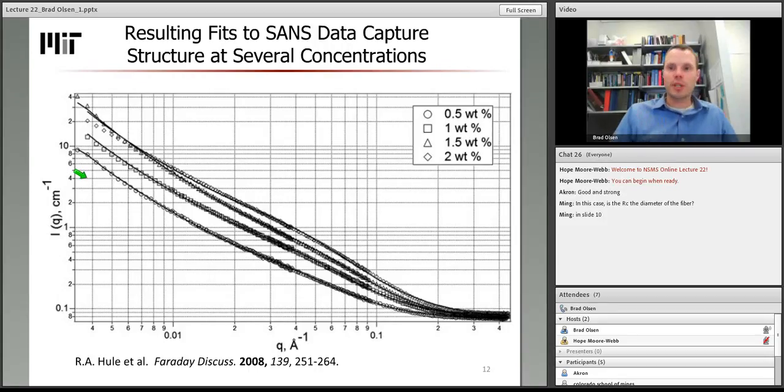And so this is one of the really interesting aspects where understanding structure and gelation is extremely important in order to answer the question, why do these gels form at so much lower concentrations than the block copolymer gels? And in particular in the fibrillar gels, because we have these highly extended cylindrical fibers, you can imagine these cylindrical fibers essentially forming struts or beams in the gel that give it rigidity, even at a relatively dilute concentration of these reinforcing structures. And so you can get gelation at a relatively low concentration of the gelator.